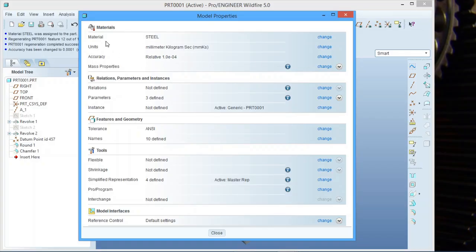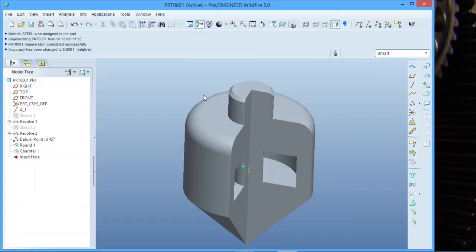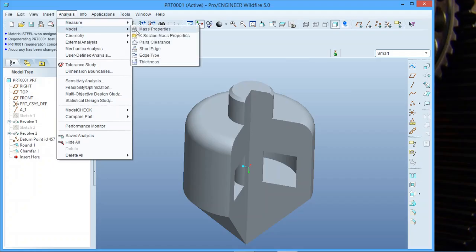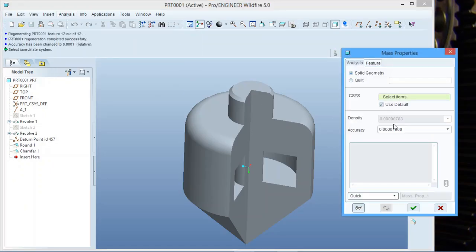So again, this one you can choose a material and it will give you density. This one you're going to enter your density and it will go there. Then in saying that, now I'm going to go back here and say mass properties, and see that it's already put in its own. If you go back in the video, you'll see this was 0.2 something. So now that is the correct mass for steel.